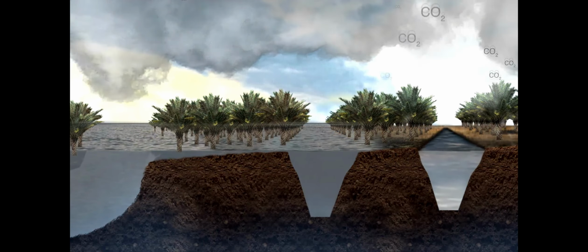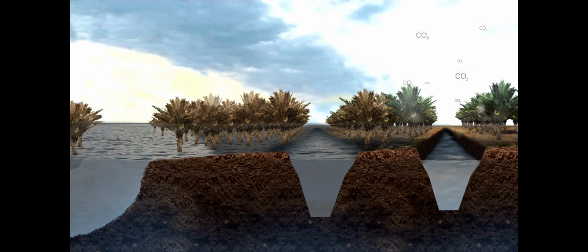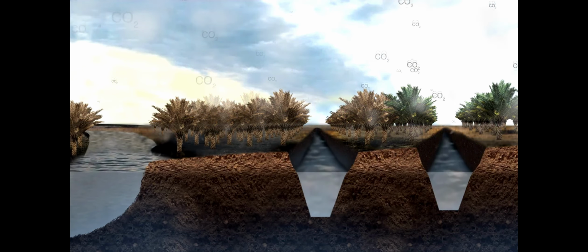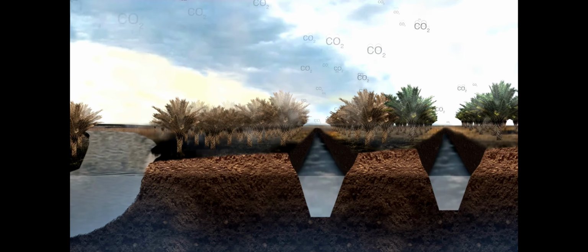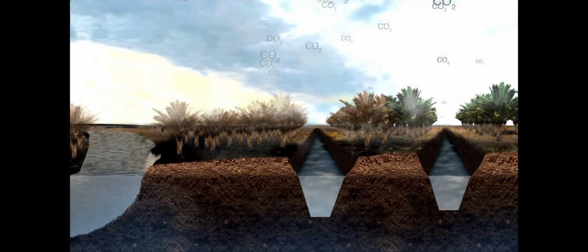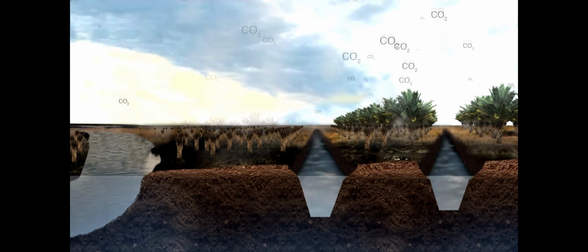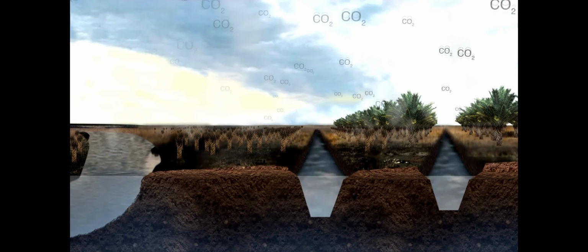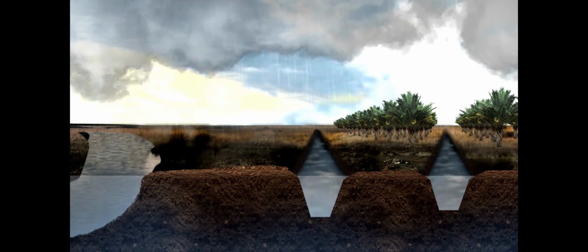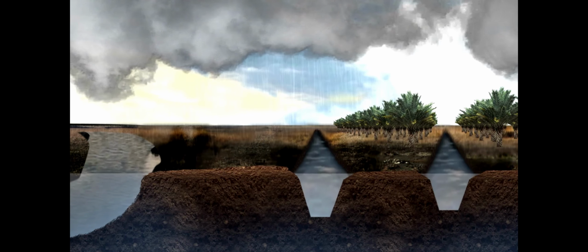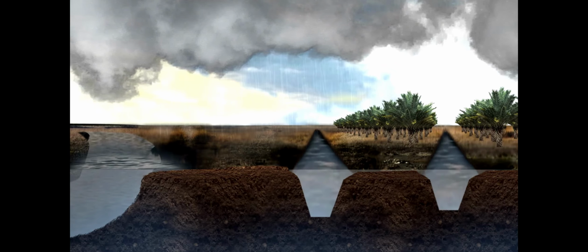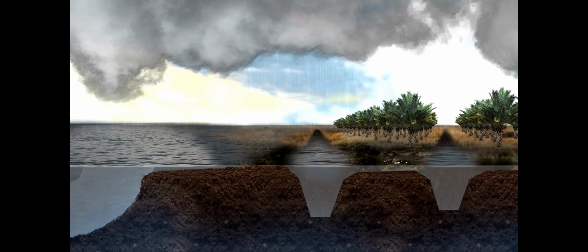ground surface to sink. The miraX subsidence tool is designed to help users better understand this process in the Duurswold peatland area in the Netherlands. It allows you to simulate how peat subsidence evolves under different surface water management scenarios using a simple numerical model. The tool also estimates the amount of CO2 emissions that can be avoided by raising groundwater levels and slowing peat oxidation, effectively showing the climate benefits of improved water management.